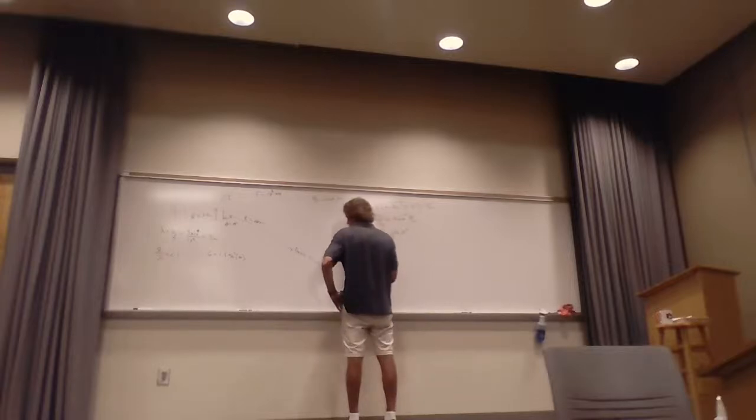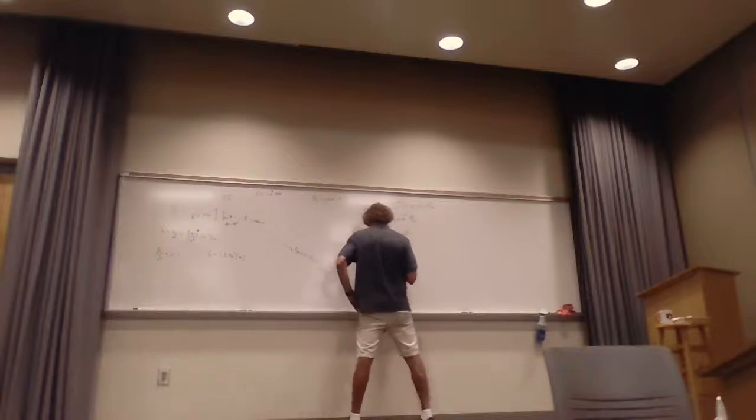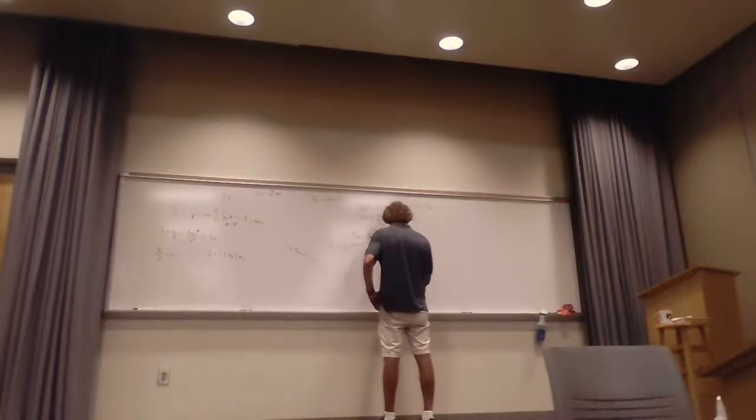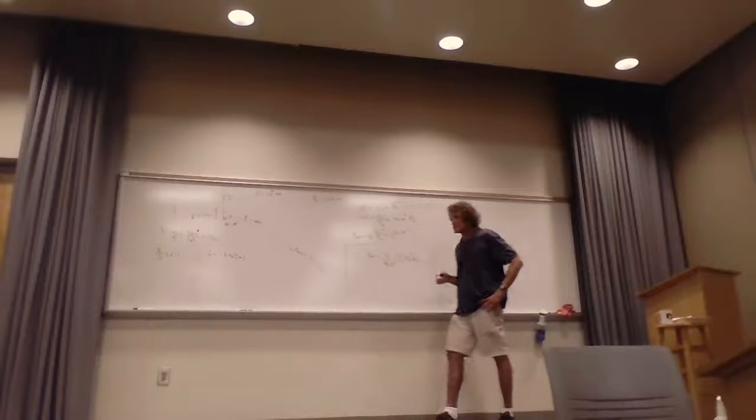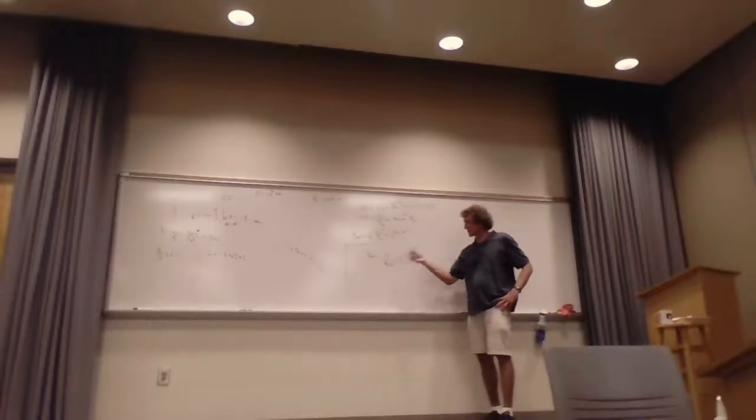I know that the power density out here, if it's a short dipole, average power density is equal to total power over 4 pi r squared. That's the isotropic. And then you multiply it by the gain, which is 3/2 or 1.5 times sine squared of theta. That's just checking boxes to get total power, right? Correct, class? This is nothing tricky if you look.